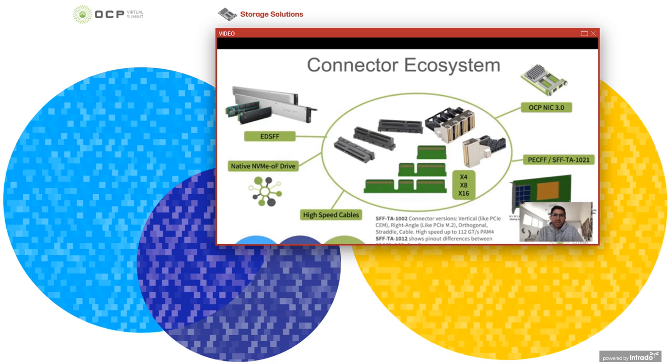Really the awesome thing about EDSFF is it uses this high-speed connector. So what you can see here is there's a by 4 variant, this one on the top, a by 8 variant with the 1 notch, and a by 16 variant with 2 notches. And they're all fully interoperable. So you can take a by 4 and plug it into a by 8 or by 16 slot. That's typical like a chem drive today, but it's also backwards compatible the other way with the notch. You can see you can plug a by 8 device into a by 4 slot if it is mechanically and electrically compatible.